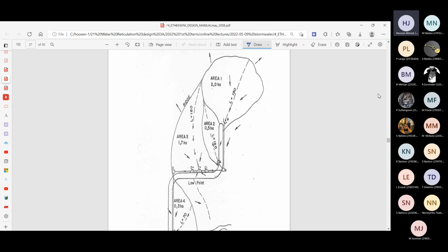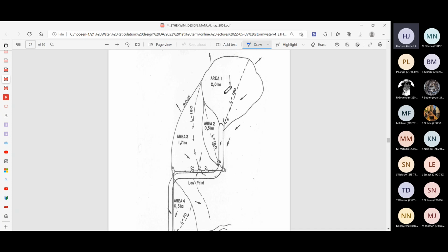If you're designing a stormwater reticulation, in all likelihood, you would have probably seen the area, or maybe you would have walked through it and visited the area to determine the kind of vegetation and the slope of the ground and the features that are there. Or you might even have looked at it in today's times, it's quite easy. You can look at Google Maps and pick up information from there.